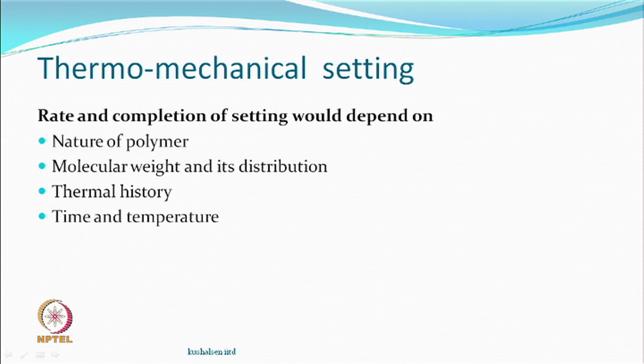polyester melts at what temperature? Polyester, that is PET. All right. So, 250 and above, and nylon 6, all right, 215, 220, and polypropylene 160 to 170. All right. So, based on what polymer you are looking at, temperatures will have to change, and that we are not talking about melting temperature, by the way.